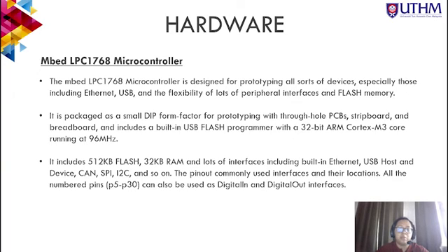It is packaged as a DIP form factor for prototyping with through-hole PCB, strip board, and breadboard, and includes a built-in USB flash programmer with a 32-bit ARM Cortex-M3 core running at 96 MHz. It includes 512 KB flash and 32 KB RAM, and a lot of interfaces including built-in Ethernet, USB host and device, CAN, SPI, and I2C, and so on.